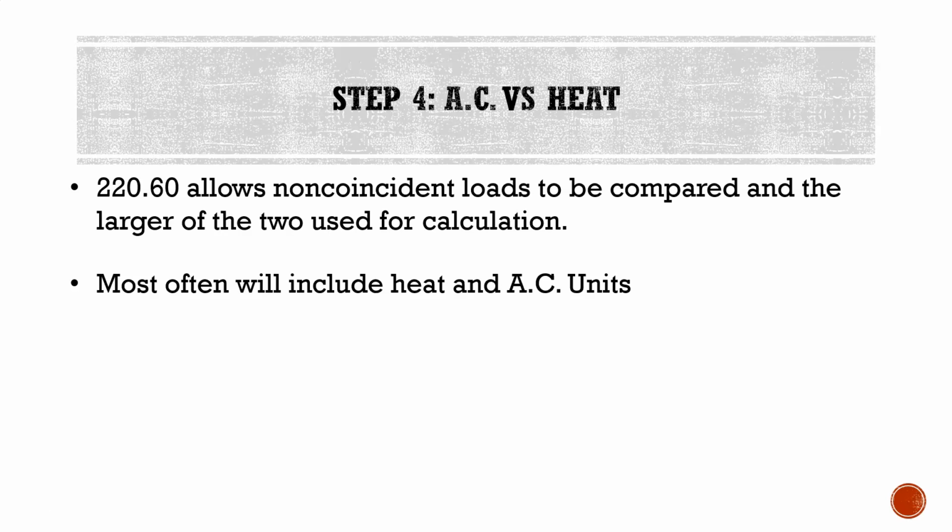In order to do that, it being a 240 volt single phase motor, all we would have to do from our motor load calculations, if you recall, is go to table 430.248, find the FLC of the motor. Everyone should be familiar with Ohm's law at this point. When we have amperage and we have voltage, we just multiply those together. That gives us wattage. And we just divide wattage by 1,000 to get our kW.